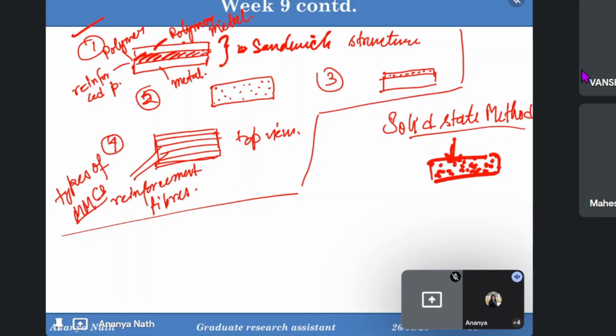There you can control the microstructure because you are providing the energy, so the melting will not take place, but all the atoms of the metal will be energized, and there will be some temperature gradient and some heat flow, and these things will be for a very short period of time. This is how you can control the phase transformation and the microstructure basically. So AlSiC is a well-known composite made by such a high energy, high rate process.